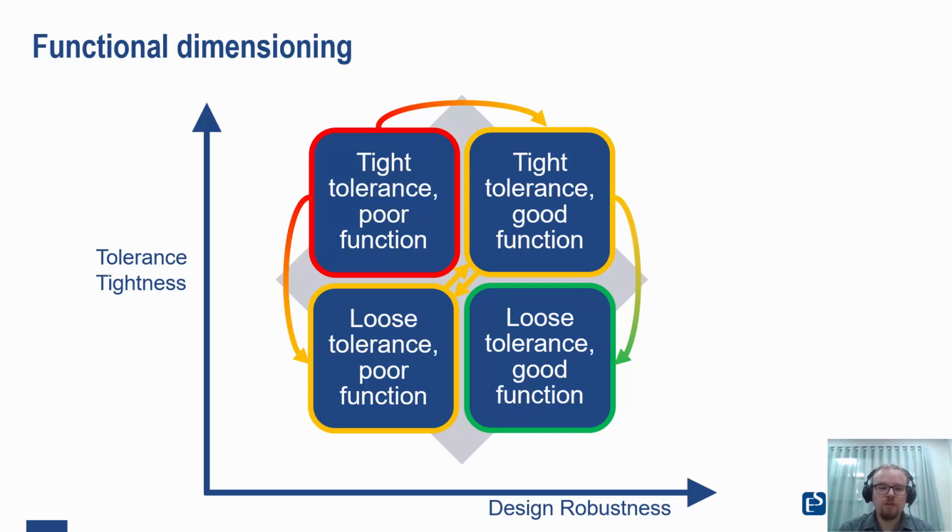This is a really important concept because we don't necessarily have to use tight tolerances everywhere to do that. There are often opportunities to loosen our tolerances. And ISO GPS gives us lots of opportunities to do that. By removing ambiguities in coordinate dimensioning, we can often specify looser tolerances, but more precisely specify what it is we want from our part. This enables us to specify the loosest possible tolerance and have no impact on quality, still maintain good quality in our products.